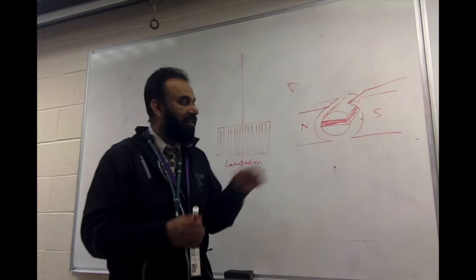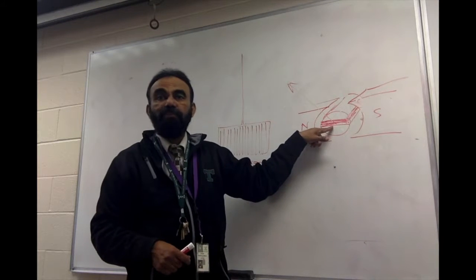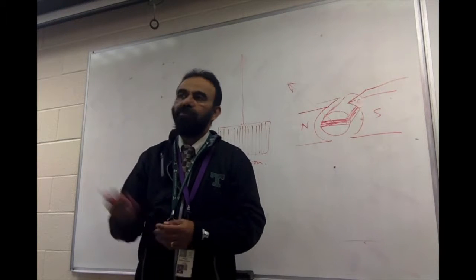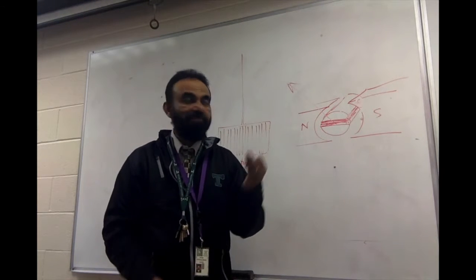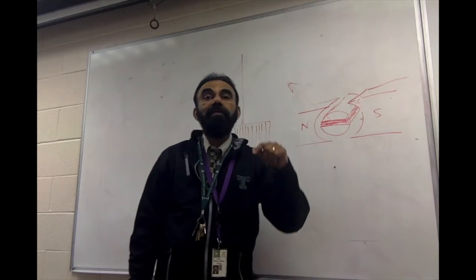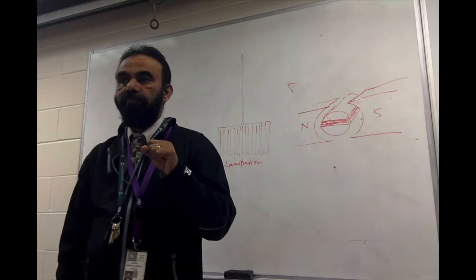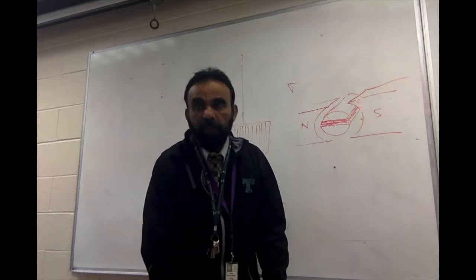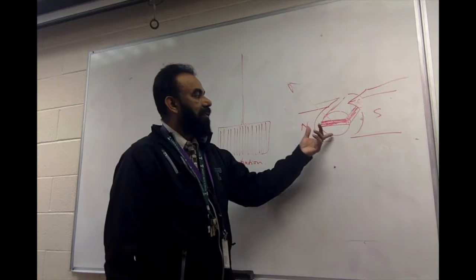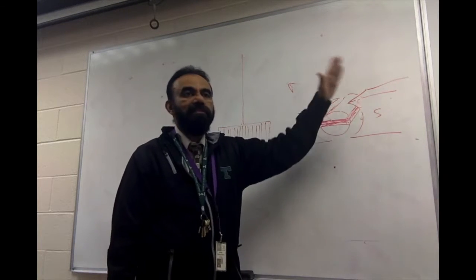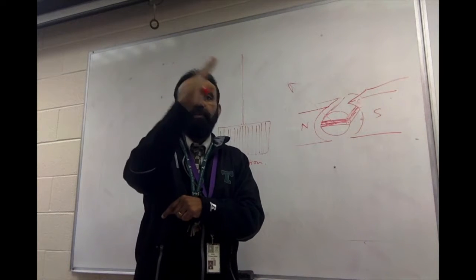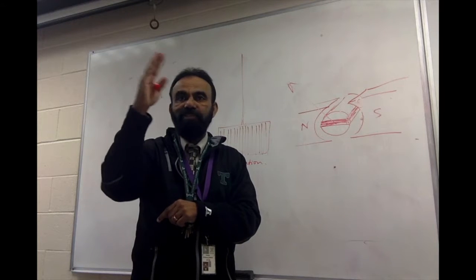To strengthen the magnetic field strength inside here, because this is a ferromagnetic material, you want more magnetic field inside the coil. So we want to strengthen the magnetic field. That's the second objective. The third reason as to why this is sitting here is to provide critical damping, something that you've seen before, last year. Critical damping is not letting this pointer oscillate on both sides of the real current value and then swing forever and finally lose its energy and come to rest.